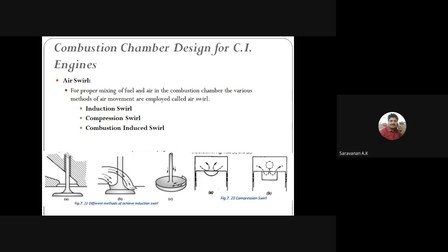This results in high power, better efficiency, smooth and noiseless engine running, and a shorter delay period, which reduces the probability of knocking. So the design is very important. Why? Because air swirl is very important.